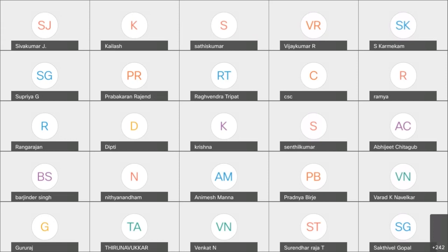In case it is a complex component like your microcontroller, you also need to understand that the microcontroller is a general component which may have a number of peripherals and components. You may not be using all of them. So you need to understand what you are not using in the microcontroller, and based on that, you can deduct that failure rate from the overall failure rate, and then start using it. Then I need to take my application into consideration also. Correct. Application in the sense of what components you are using. For example, if you are not using a CAN controller, then the CAN controller related aspects within the controller you can eliminate.